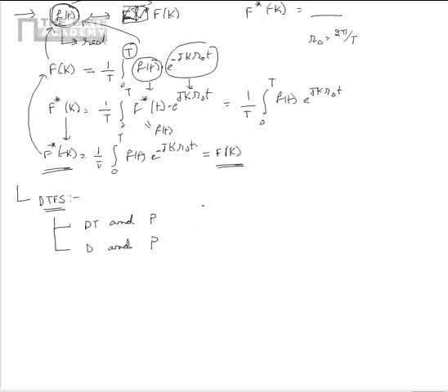So here suppose there is a signal x of n given, its frequency representation is given by DTFS. Here please note that x of n is a discrete time signal and is periodic with a period N. Then its Fourier series representation DTFS is given as x of k. Please note that x of k by its nature is discrete and periodic.